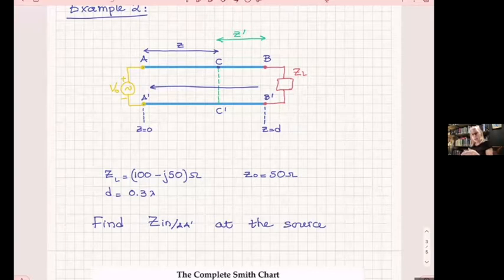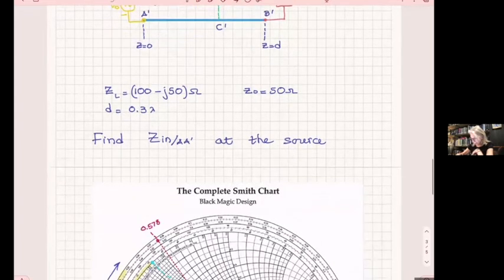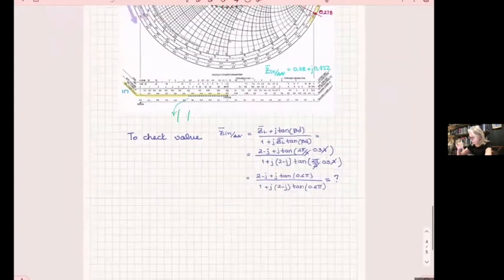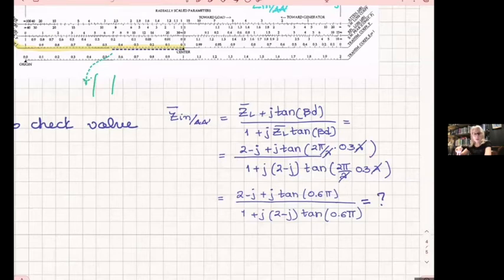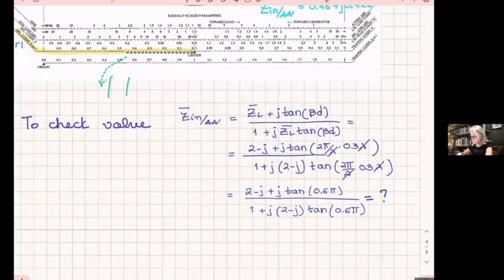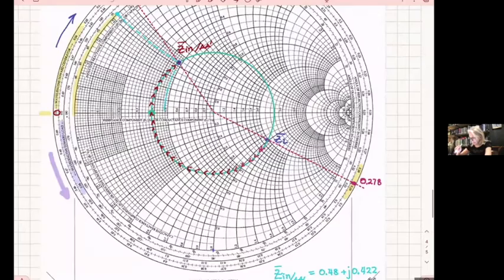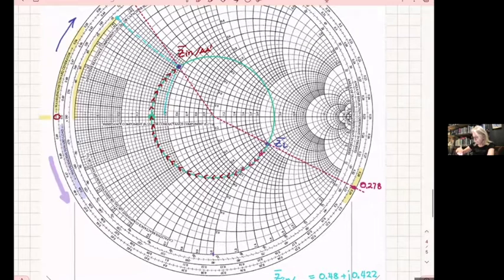And then when I look now towards the load, I see an equivalent impedance there, which is here, what we would normally use on paper. You see this formula. That's how I would calculate that input impedance at AA prime from the load, and this is all normalized, from the load at the end of the line and from the distance from the load. So that's the formula. However, on the Smith chart, to find this, I have to follow this process.